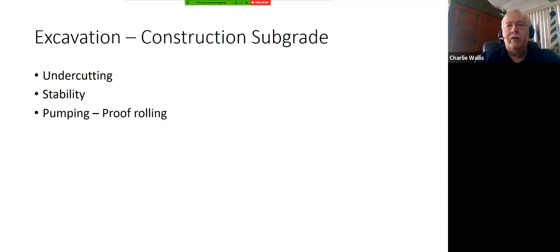Now, again, once you get to excavation subgrade, you want to make sure that the surface there is stable, that it's not pumping. Now, proof rolling, you may not be able to get large equipment in there. If you have the ability to do it, it would be nice to have a large dump truck that's full, with tire wheels on it, so that you're concentrating the force on certain areas to see if the soil stands up or if it pumps and moves. And if you can't do that, you could even just walk it and press your heels into the soil and see if it supports you or if it's giving way.